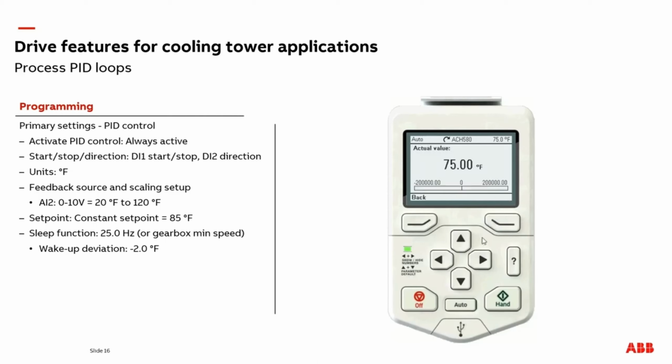I'm going to go ahead and leave it at a constant set point and adjust it here. For tuning, we'll leave tuning at the defaults for now because it's just a demo unit. That is where you would adjust it in a real-life situation. For increased output, I wanted to increase the speed of the fan when the feedback gets greater than the set point.